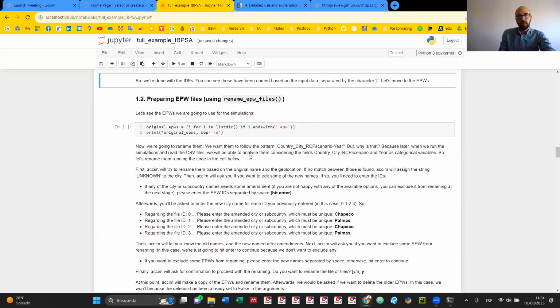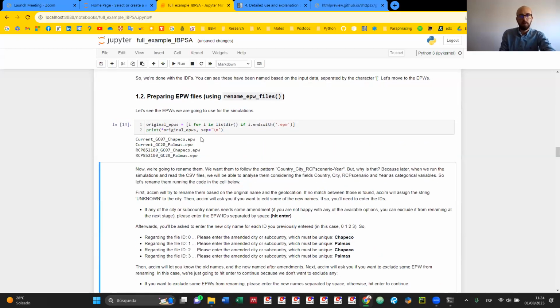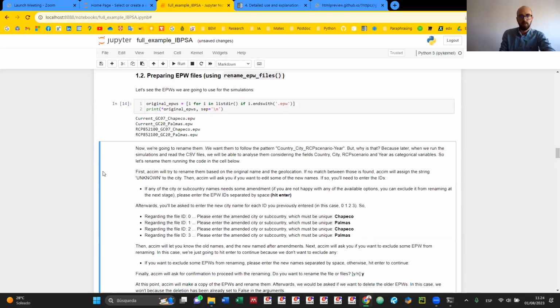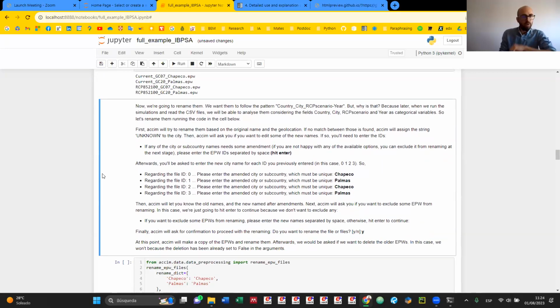Okay, next step, let's prepare the EPW files. And this is done by using the class rename EPW files. The EPW files we have are these 4. So now we're going to rename them. We want the new name to follow the pattern country underscore city underscore RCP scenario underscore year.